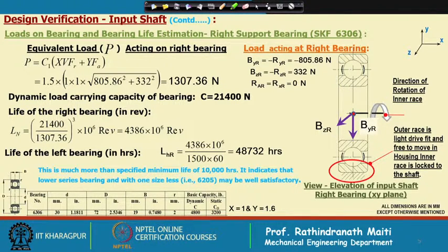So, that is acceptable, and there are also different types of locking arrangement possible. In fact, after the bearing we can put a bush there, and after that a sleeve, and then we can put a coupling. Okay. So, when we make the detailed drawing or plan view of the housing, we shall discuss this matter again.